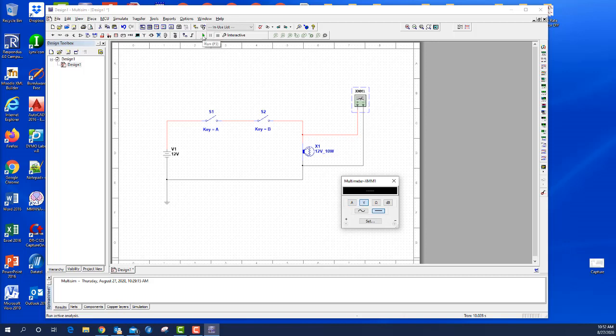So let's go back and run the circuit. So I press play, and you can see that Multisim tries to mimic real circuits, and in case you don't know, this is a very, very tiny voltage. It might look big to you, but nV stands for nanovolts. A nanovolt is very tiny. That is actually much smaller than any voltmeter can measure. So for all practical purposes, right now it's measuring 0 volts at the lamp.